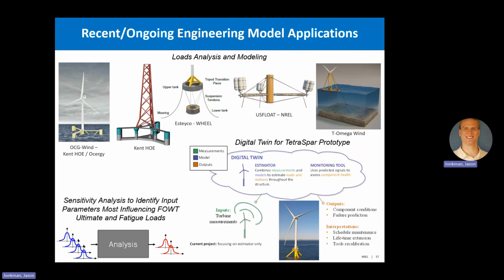So with those few inputs, what we were trying to do with this model is say, can we extract things like the tower loads, and can we do that right, even though we're not measuring the tower loads directly? Through things like linearization of OpenFAST, and Emmanuel has a whole toolbox of capability around this digital twin space, basically using it in an operational sense to track things that happen in real time.